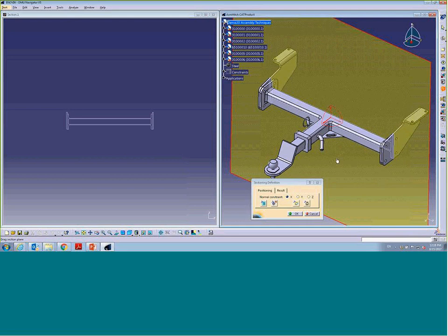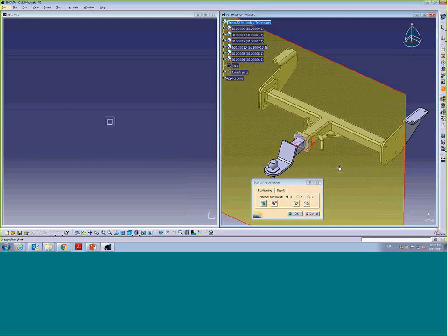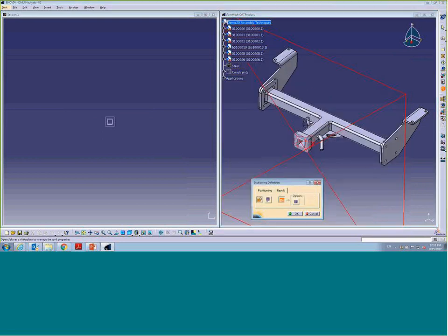We can place the plane exactly. For instance, if I want to snap this plane to this surface, you would select geometrical target, click plane, and it's snapped. If I go to result, I can also view it as volume cut. Okay, shows me the cross section, and on the right side this.